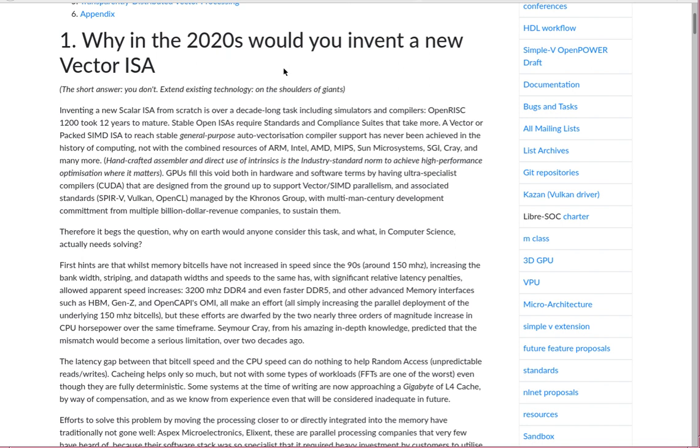You can utilize the schedule to multiply and accumulate, the accumulate register becomes an accumulator, and you can do arbitrary in-place matrix multiplication, not limited to radix 2.